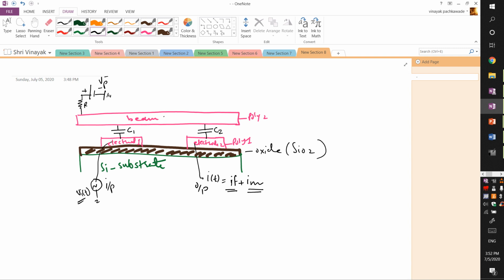So the feed through path is going to be like this. I have this one and then through this one I have this one. So obviously these two capacitances are in series, so, let's say C1 and C2 are equal, the effective capacitance is C over 2. So this is called a two-port combination, a two-port mechanical transducer, as compared to the previous one, which was a one-port transducer.